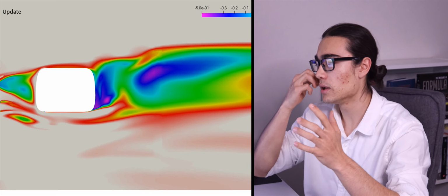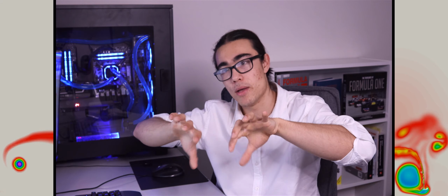Okay, so generally the geometry has done what I wanted it to do. We set up this counter-rotating vortex pair just above the front wing main plane to achieve some outwash, which we could see, and also use the strake to limit some of the tire squirt coming out and better manage the wake in that region. So as always, I like to think about the contours that you can use to show the major differences, so we can perhaps know how to iterate the geometry further in a more efficient manner.